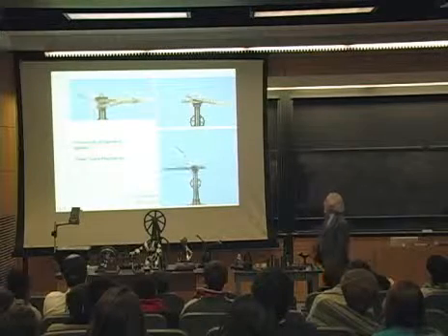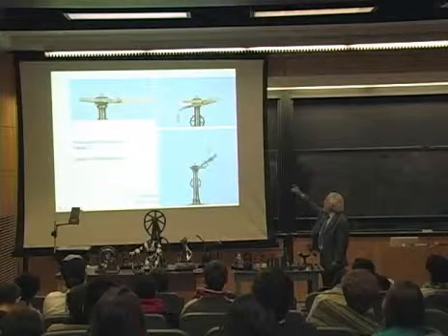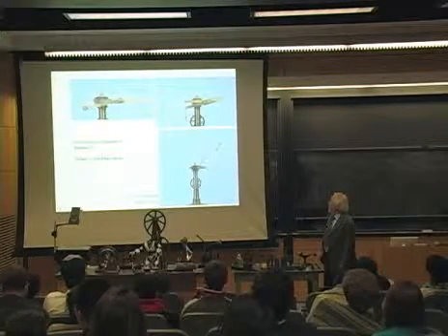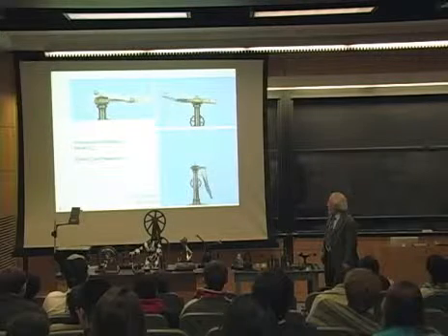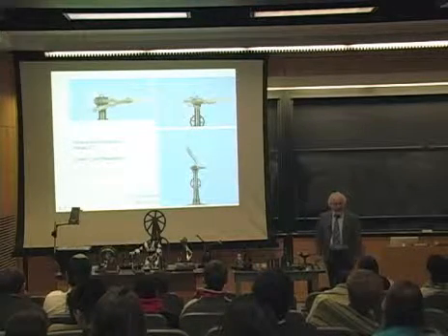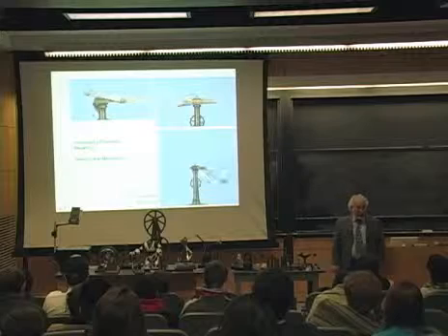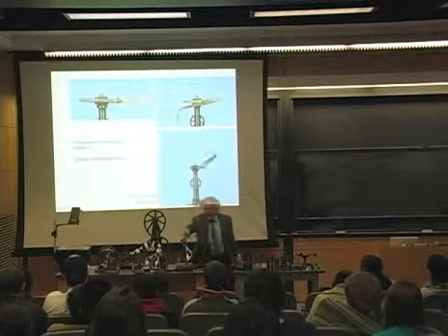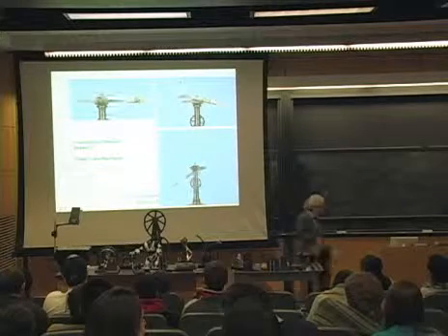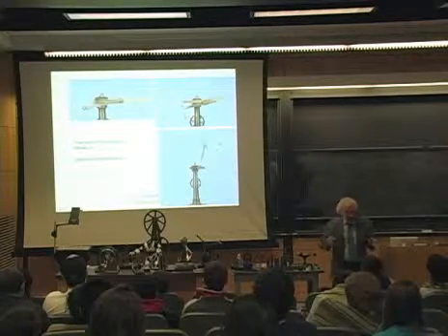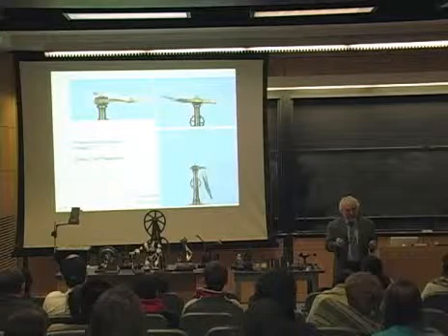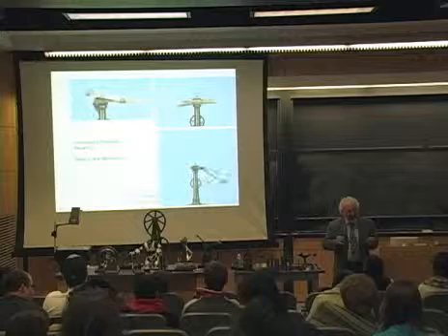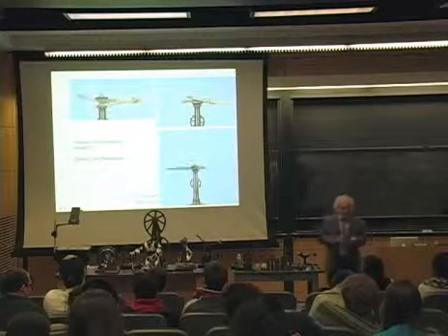On the other hand, you can have these others where you fix the connecting rod or one of the other links, and you get a different realization of the mechanism depending on which of these you ground. So not only do you have the idea that you can create different mechanisms with certain numbers of links and joints, but you also create mechanisms by which one you ground and which one you move. Okay.